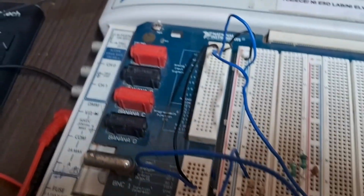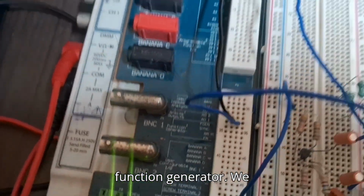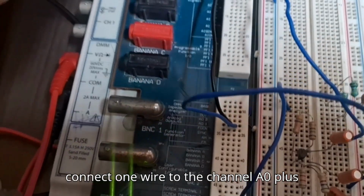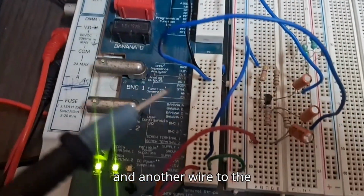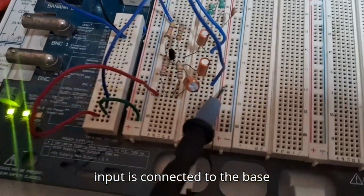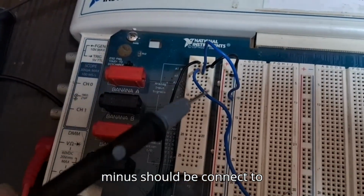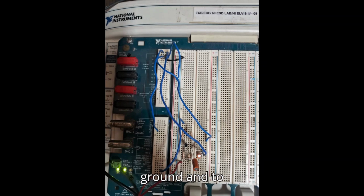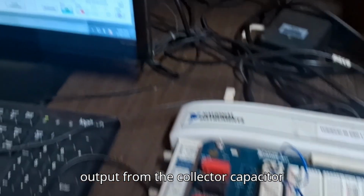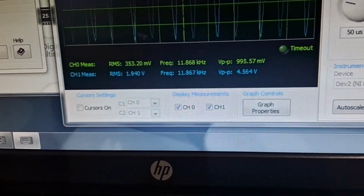To generate the input signal, we use the function generator. We connect one wire to the channel A0 plus, and the input is connected to the base capacitor, and A0 minus should be connected to ground. To view the output, we take the output from the collector capacitor and connect it to the A1 channel.